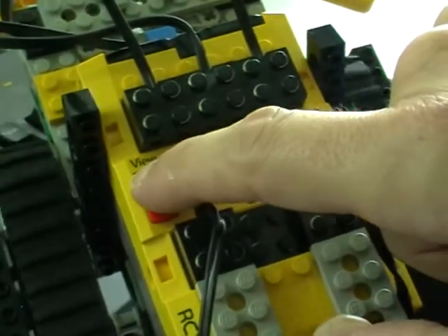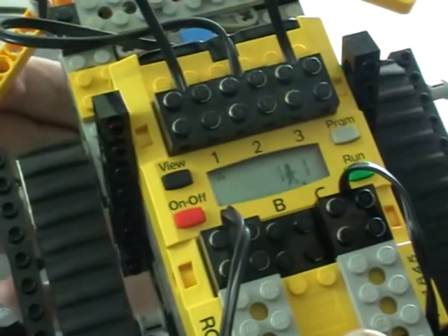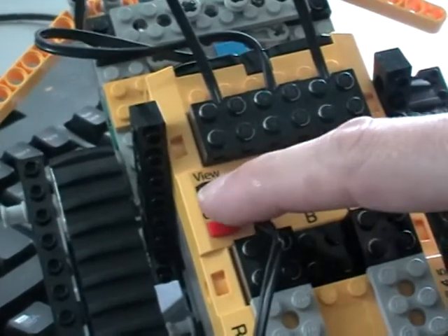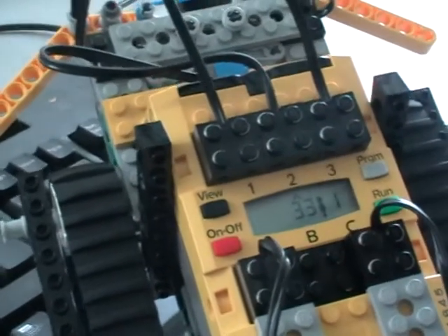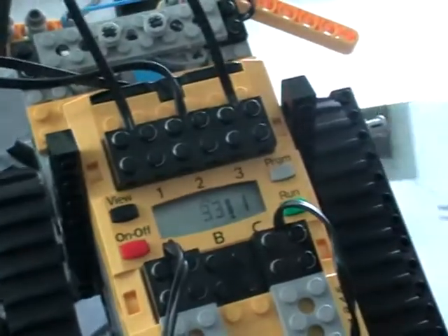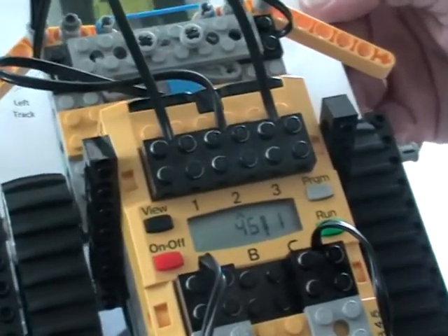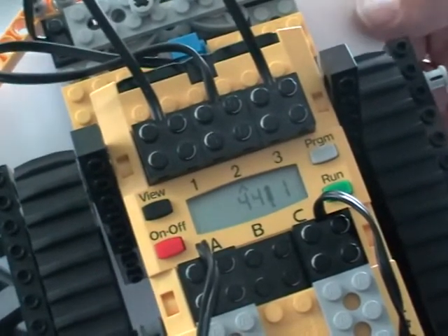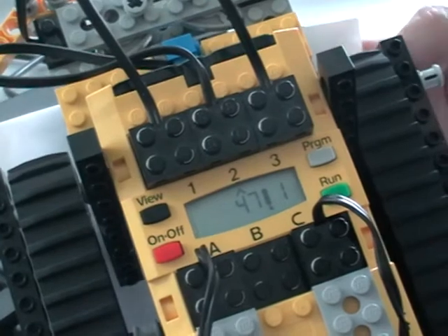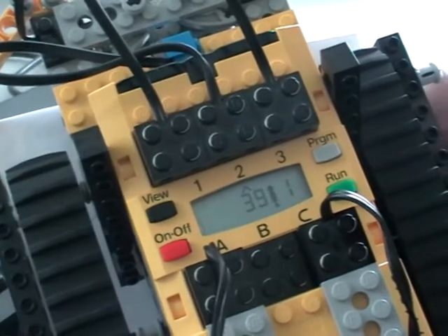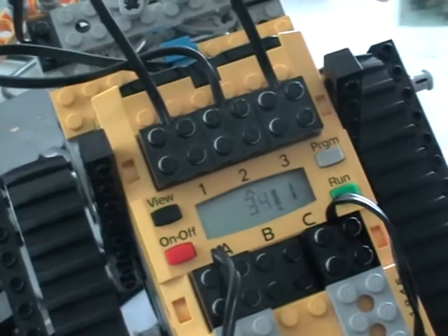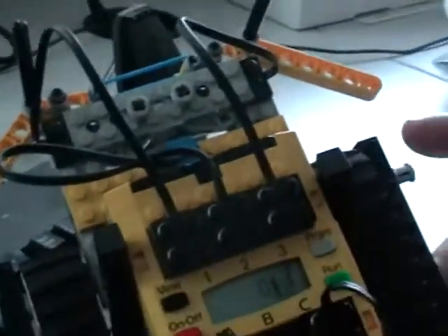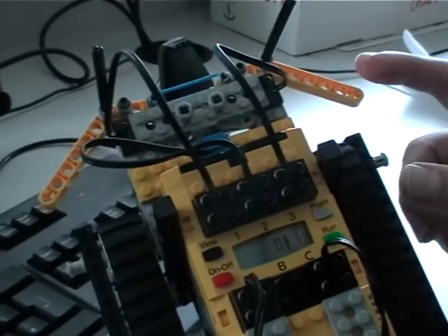So if we look firstly at sensor 1, we'll see now we get binary values of 0 and 1. If we look at our light sensor, currently we're getting a reading of 33, and we're going to use firstly a white piece of paper. We get 45, and we're going to move it to a darker piece of paper, and we're getting around 38, 39. So you can see there's a difference in the reading. And we'll also look at sensor 3 quickly, and you'll see once again we get binary values.